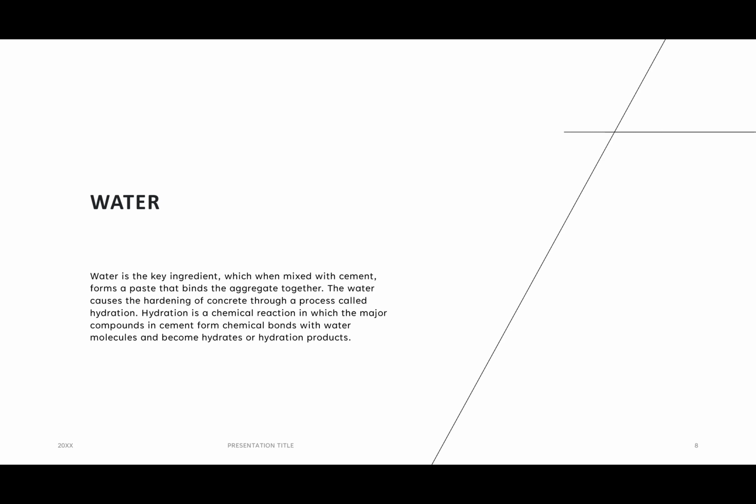The amount of water in concrete controls many fresh and hardened properties in concrete, including workability, compressive strength, permeability and water tightness, durability and weathering, drying shrinkage, and potential for cracking. For these reasons, limiting and controlling the amount of water in concrete is important for both constructability and service life.